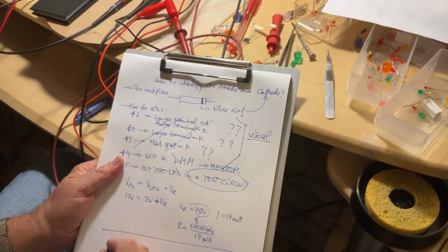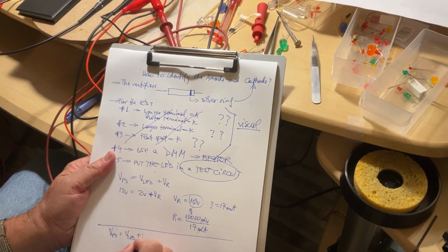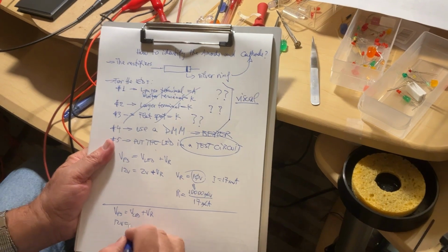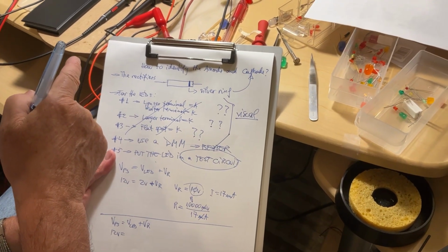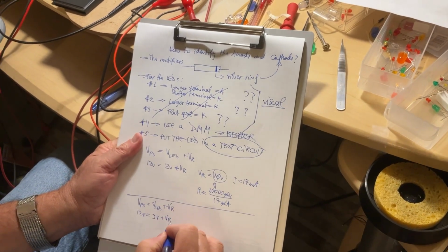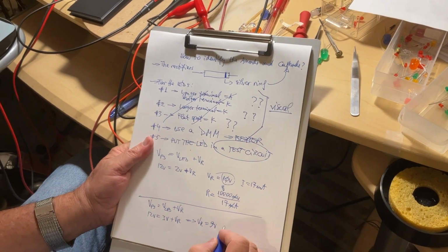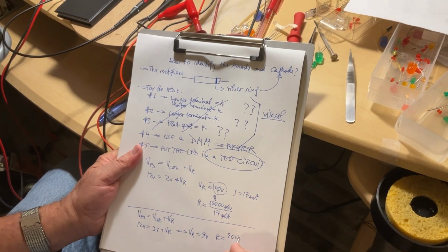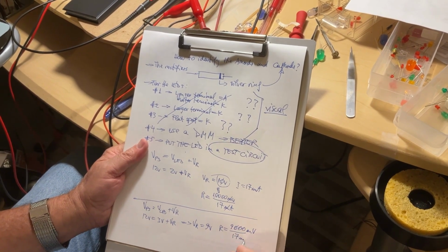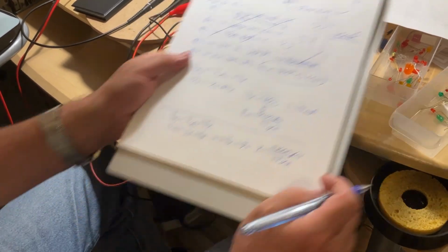We do the same calculation. Voltage of the power supply is the voltage across the LED plus the voltage across the resistor inside the socket. 12 volt equals, hey, this is a white LED. For white and blue LED, we use 3 volts instead of 2. So the voltage across the resistor is going to be 9 volt. So this time, if I want to find the resistor, I'm going to convert 9 volt into millivolts, 9,000 millivolts, over the same 17 milliamps. Milli and milli disappear, and volt over amps, I'm going to get the answer directly in ohms.